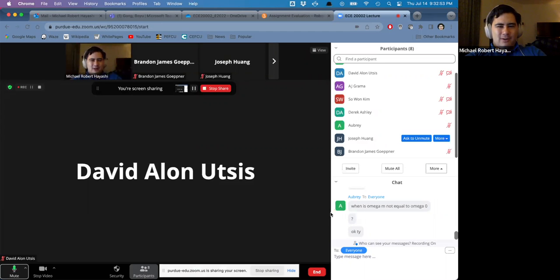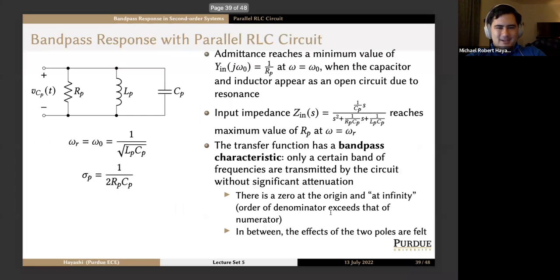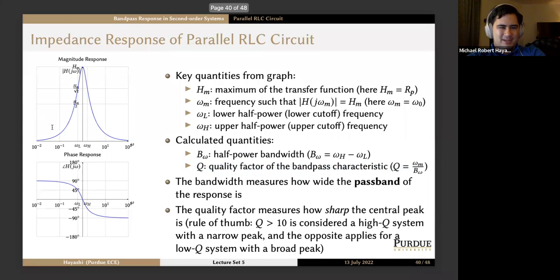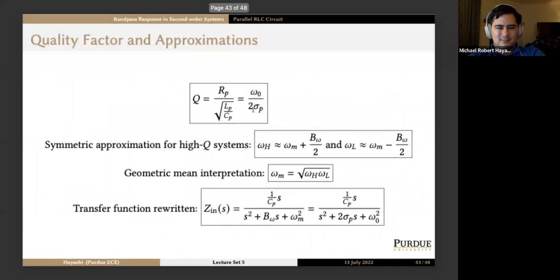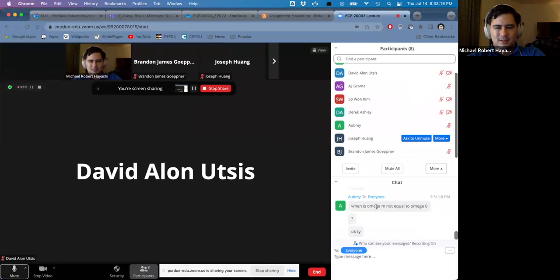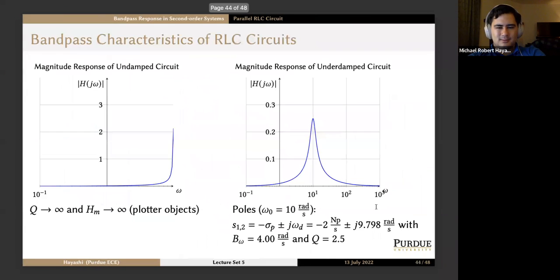You have to figure out where the circuit resonates in order to find where the imaginary part of impedance or admittance goes away. And that will be the place where you have the maximum of your transfer function, because the maximum of the transfer function is where maximum power transfer occurs, which happens at the resonant frequency. But very good question. I had to think about that one.